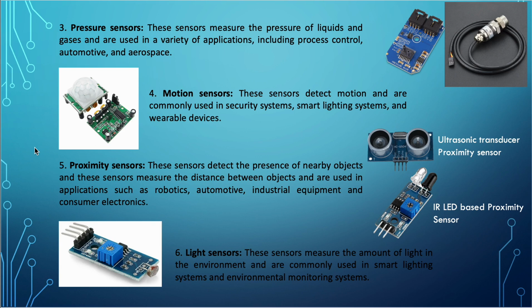You will go to its official site and see, or take the data sheet out and see what ranges can be achieved, what the errors would be, how strong the sensor itself is, and so on and so forth. Then select the correct sensor, right?